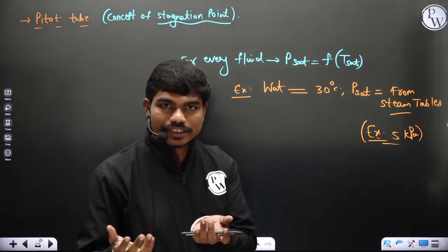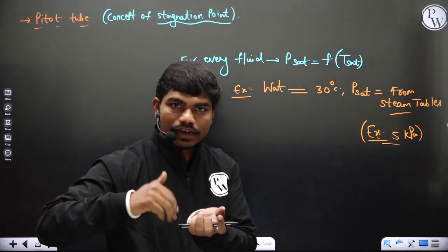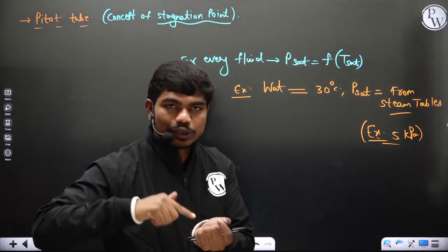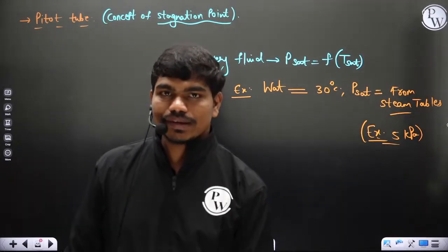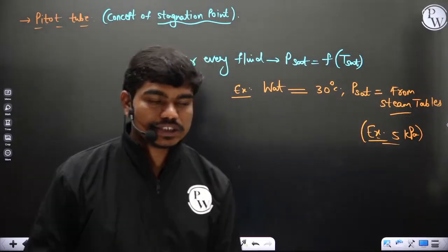If you see the operating pressures of condensers, normally it is 30 kilopascals, 40 kilopascals, in this range. Atmosphere is 100, and inside it's 30 or 40, that's it. So that's why condensers generally operate at low temperatures, and low pressures of course. Okay, low saturation pressures. Fine.